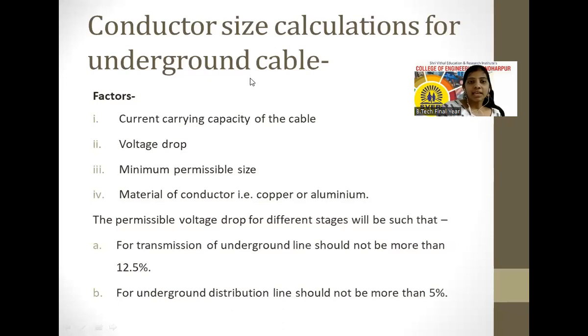The factors are listed here. First of all, the current carrying capacity of the cable. Whenever we find the actual current required to run the load, depending on that, we select the size of the conductor. So the first major point is the current carrying capacity of the cable.